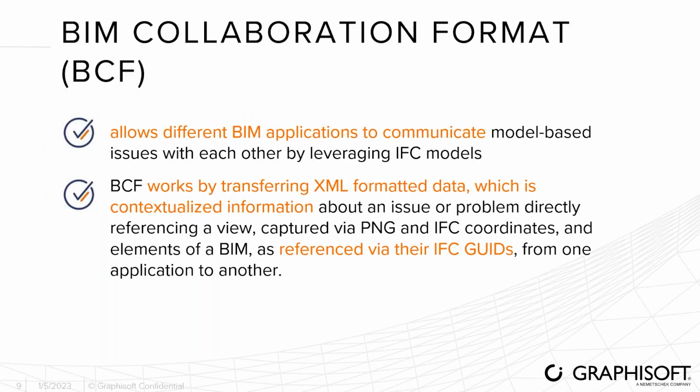So you might also ask, what is BCF? So BCF is actually a BIM Collaboration Format, which allows different BIM applications to communicate by leveraging on the IFC model. So the BCF works by transferring XML for metadata, which are contextualized information of an issue with reference via their IFC GUID.